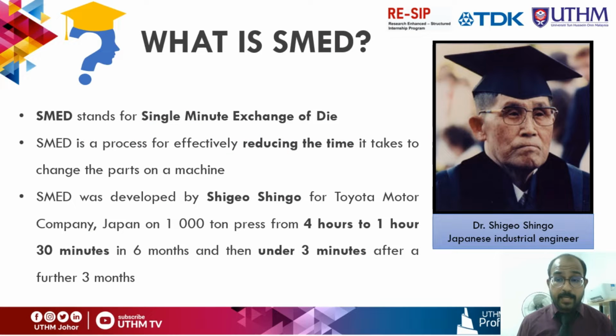What is SMED? As I said before, SMED stands for single minute exchange of die. SMED is a process or system for dramatically reducing the time it takes to complete equipment setup or changeovers. The name single minute exchange of die comes from the goal of reducing changeover times to the single digit, for example, less than 10 minutes.